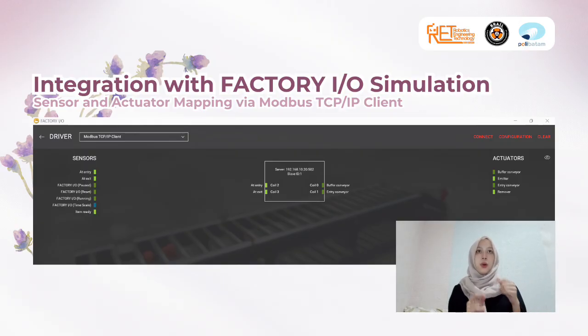In here, we choose the driver type as Modbus TCP/IP client, and there is a server that we have set before, that is 192.168.10.20 with port 502 and slave ID 1.